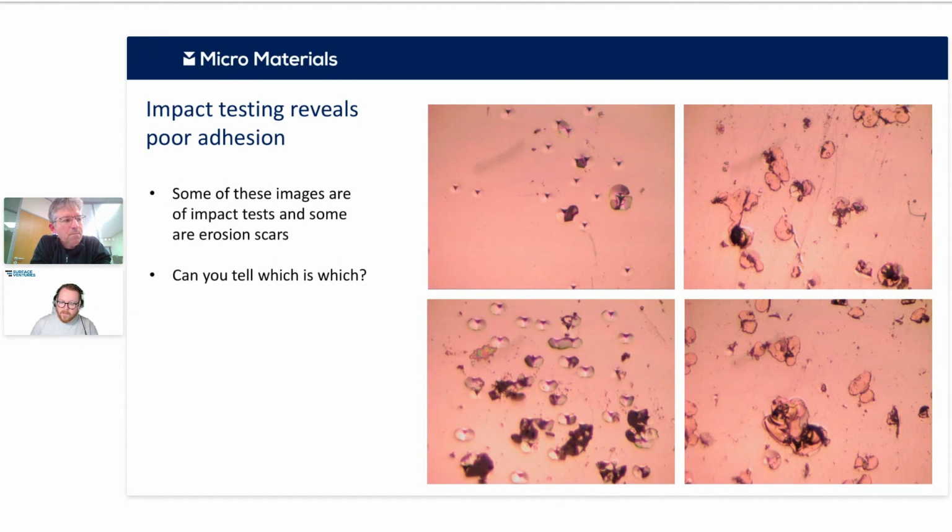Well, yes. All of the tests I showed here were normal impact, so 90-degree impact. But we have adapted it to do angled impact, which I think catches much more of this abrasion erosion combination. That works very nicely as well. You can do off angle, and we've done even up to 50 degrees or something like that. These are all possible. Different choices of different probe geometry.